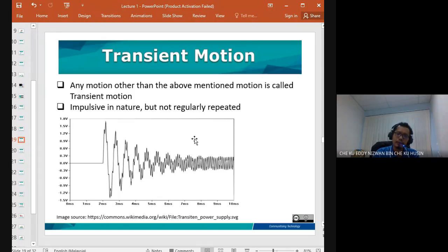So we give the impact force, or otherwise you can use random force. Those are the other two methods. This one mostly comes from free vibration. You just give the impact and then release, and it keeps vibrating. The way it vibrates depends on its natural frequency.